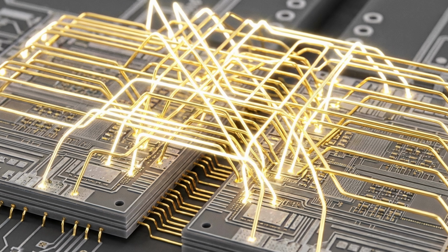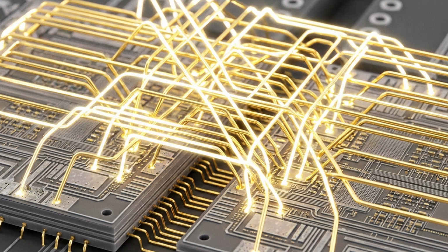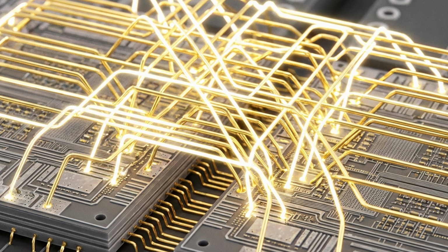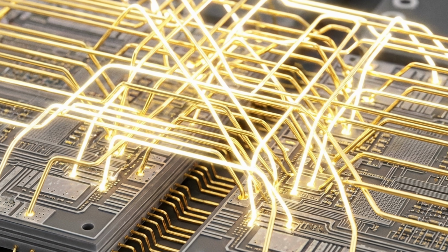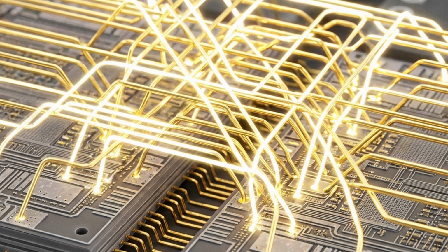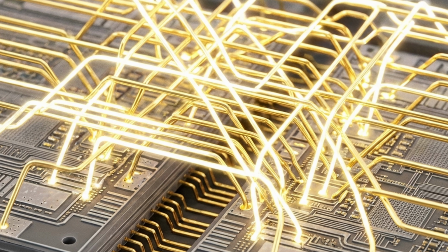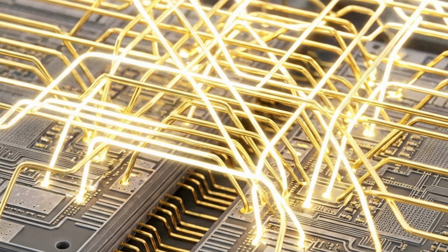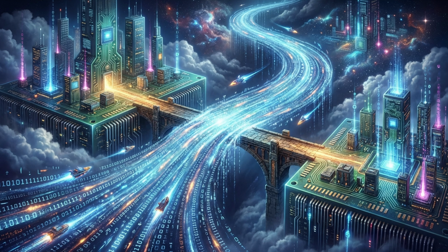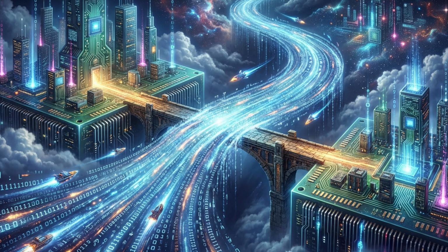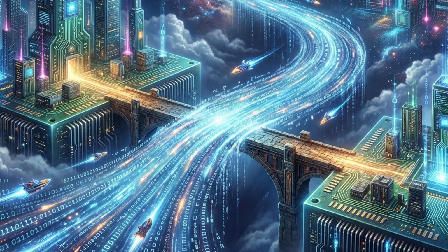Because modern semiconductor fabrication has pushed photolithography to the absolute physical size limits of a single silicon wafer print, known as a reticle limit, engineers designed the Blackwell processor by manufacturing two incredibly massive distinct dies and stitching them together with a custom power-efficient connection technology called the high bandwidth interface. This microscopic bridge delivers an astonishing 10 terabytes of bandwidth between the two halves.